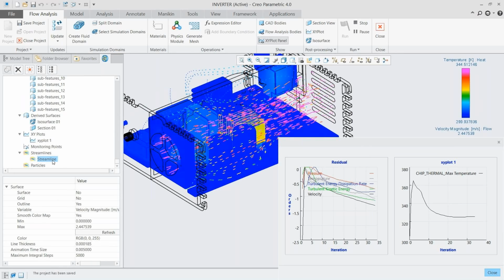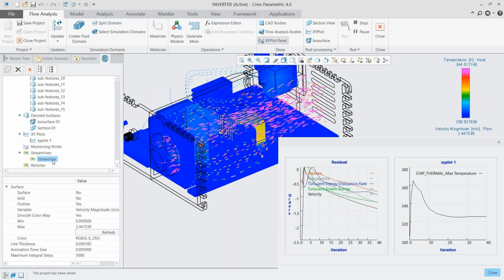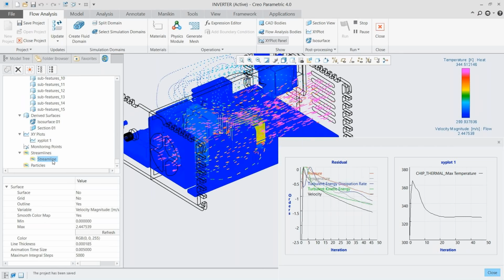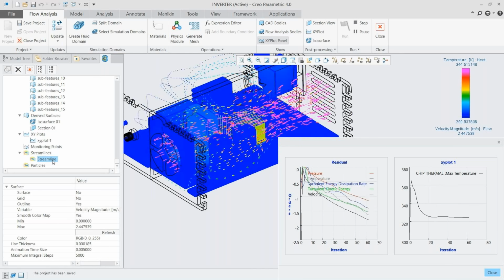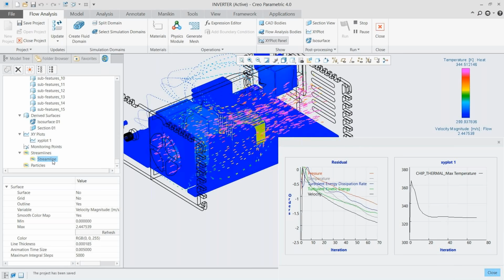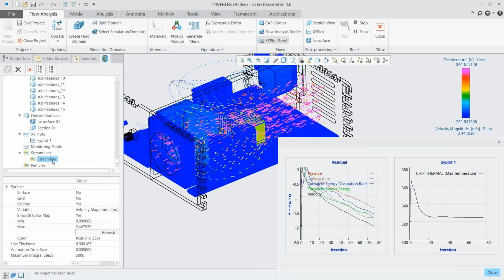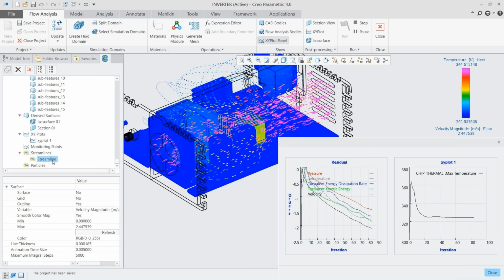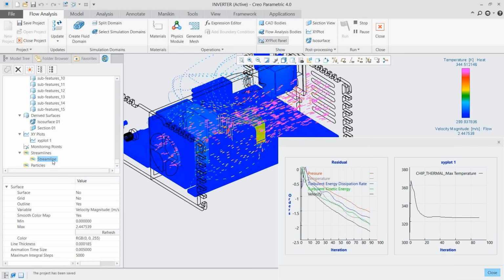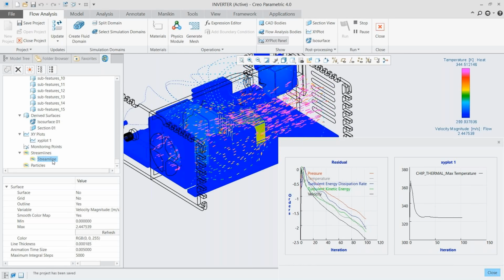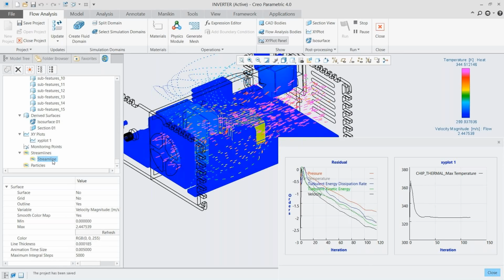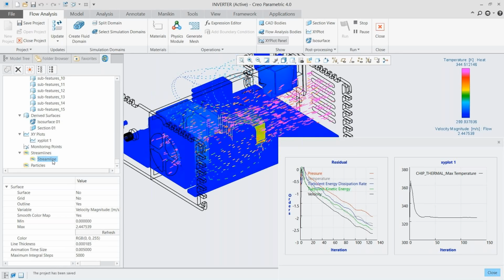First off, our steady state temperature is down from around 345 to around 325, 330, so some improvement there. And we've dropped from 400 down to around 365 for the max temperature. So we have lowered the temperature, maybe still not quite what we're looking to get to, but we are seeing some improvements just from that. And we can see in the streamlines that we're getting a little bit more of a steady flow from the inflow to the outflow. We are still getting a little bit of loss over there in the center, in the turbulence around the chip, but overall we're having better streamline from entrance out to the fan.